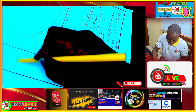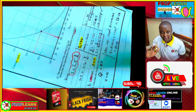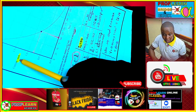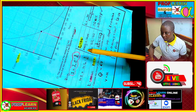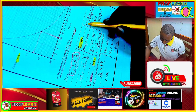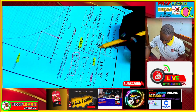Remembering that 2.4 is basically milliamperes. Most of the time, students are going to forget that these values that are given here are in milliamperes, and they end up using 2.4 as amperes. You have to be very keen as if your life depends on this. And then if you substitute that, you are going to ultimately work this out. Our time is 100, our resistance is 5.1 kilo, and don't forget this is K, so you're going to multiply this value by 1000.